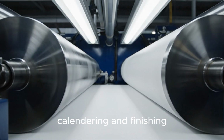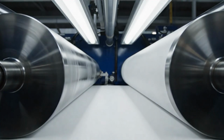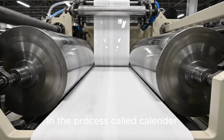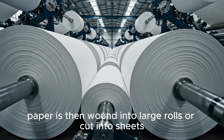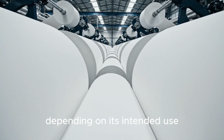Step 9. Calendaring and finishing. The dried paper passes through smooth rollers in a process called calendaring. This gives paper its final thickness, smoothness, and gloss. Paper is then wound into large rolls or cut into sheets depending on its intended use.